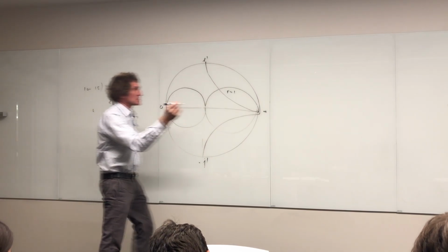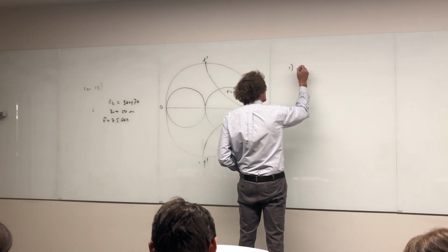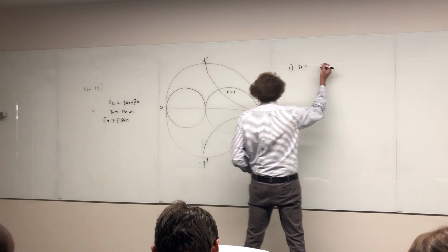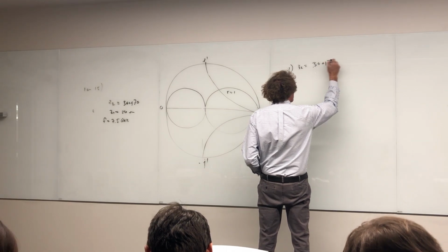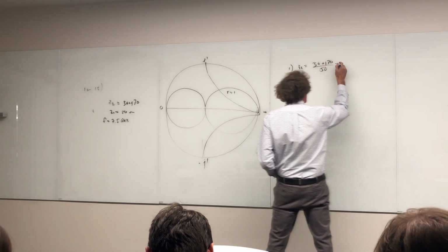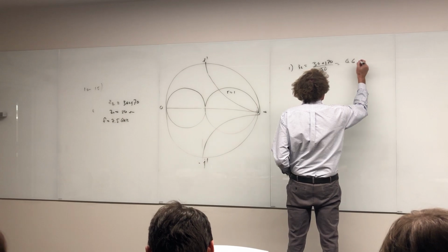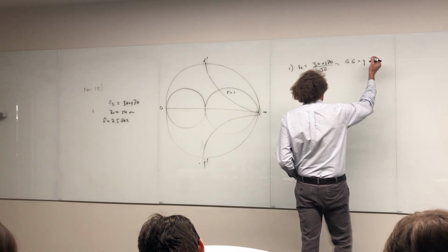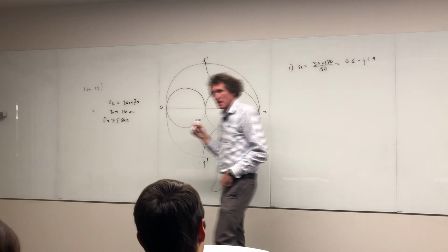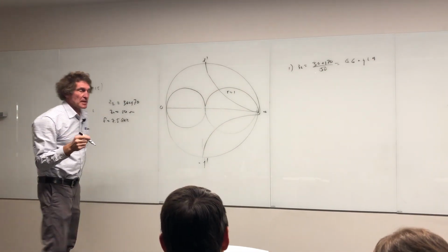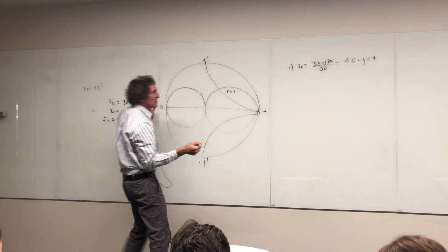All right, so first thing we do is normalize the impedance, right? So Z normalized, let me put the steps here. It's going to be ZL normalized, 30 plus J70 over 50. All right, that's 0.6 plus J1.4. Do you all agree with that, class, first of all? That's what I got. All right, now, you got to plot that. Make sure you know how to plot this. Some of that is the problem.